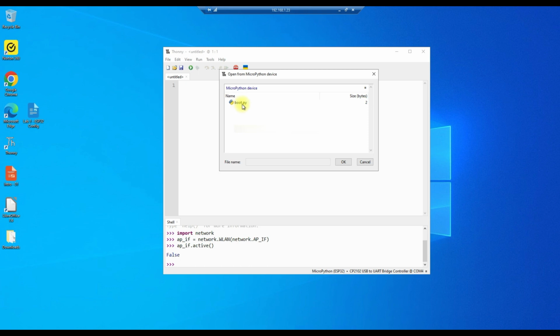That's the default file that's installed when MicroPython is installed on the device. That's the initial file that's created. Let's go into here, and this file, every time the device boots up or restarts, resets, whatever, is automatically run. So this will be where our main configuration goes for initializing the network connection and all of that.